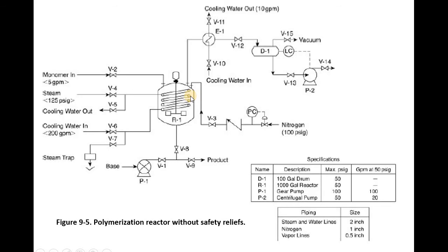Now, talking about reaction, I'm having a reaction that goes on here, and the heat is starting building up. I have vapors, I also have a liquid phase of the polymer, and of course this is a stirrer just to make sure that you don't have lumps of polymers on one side, it's all equally homogeneously distributed. And what do we have? We are trying to use cooling water to cool down that exothermic reaction, to bring down the temperature to the optimum temperature.